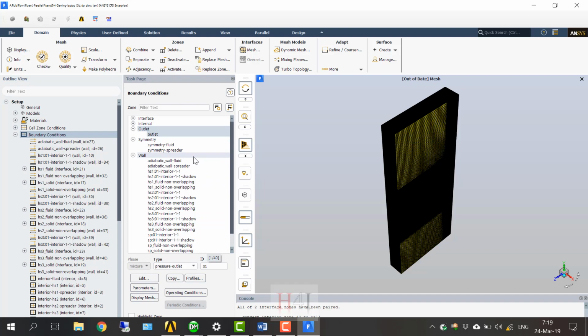So this method that you just showed us, can we define an equation for inlet? Maybe velocity. Yes, you can define a velocity profile. You have the temperature profile, anything, and you can define it as a function of another parameter in the solution. During the solution, you can define the flux as a function of the average temperature at the outlet, maybe, and you can add an if condition. If there is something, define the flux like this, and if something else, define it like some other value. And this is not available in 19.2.